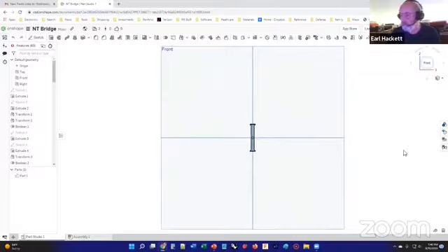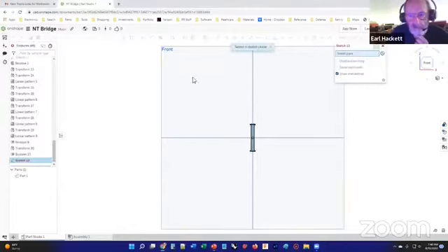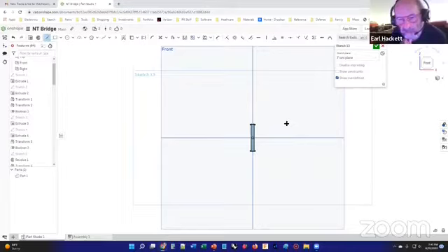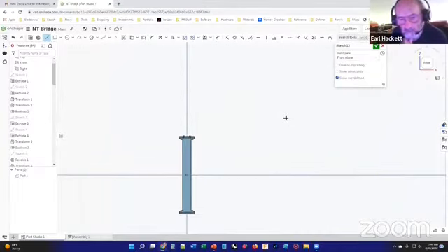Okay, we're going to start by building the, gotta get this up on here on my other screen so I can see it. Start with the knee brace. And pick up sketch. We're going to do it on the front plane. And we're going to do a line. This one here, we're going to actually have to sketch the darn thing. So we're going to start with just